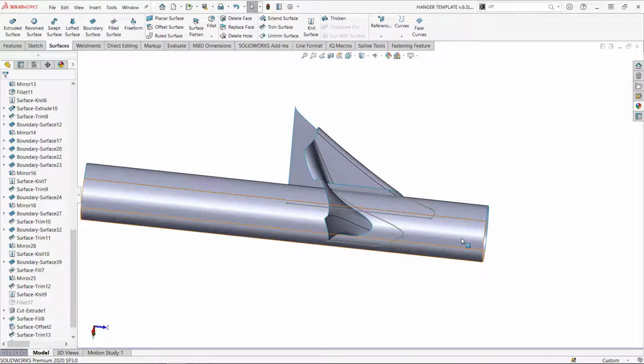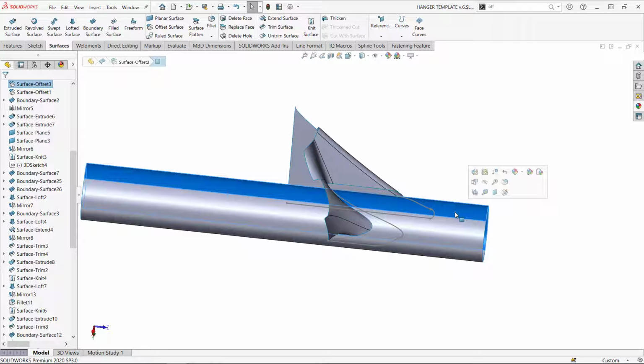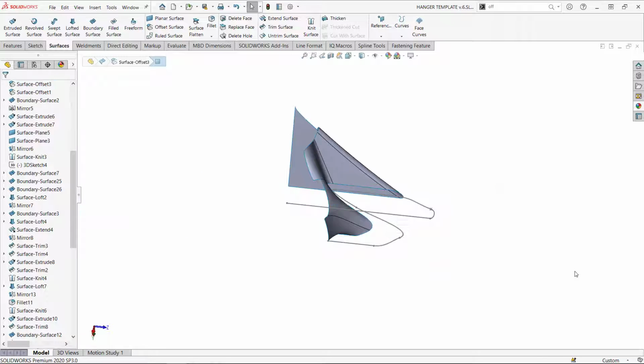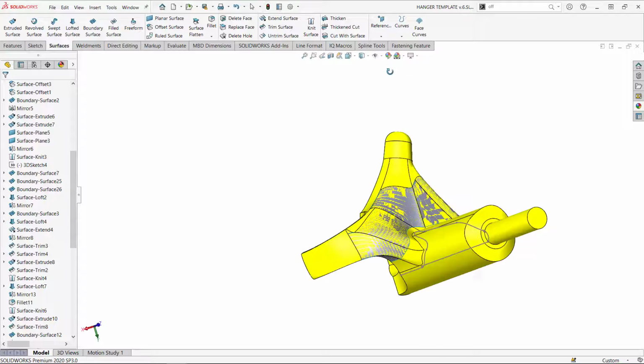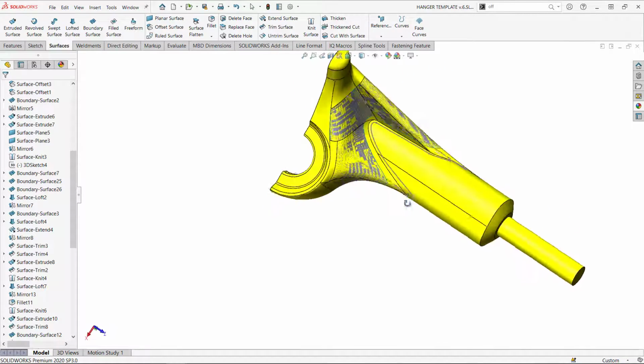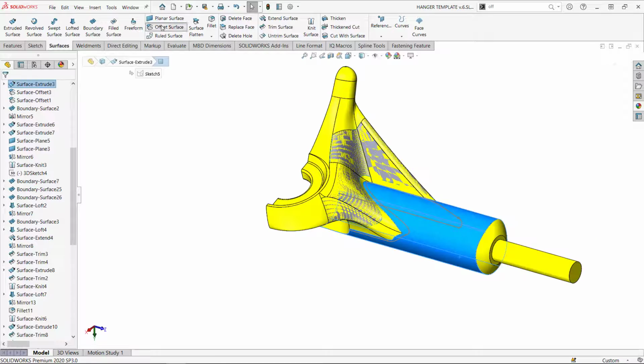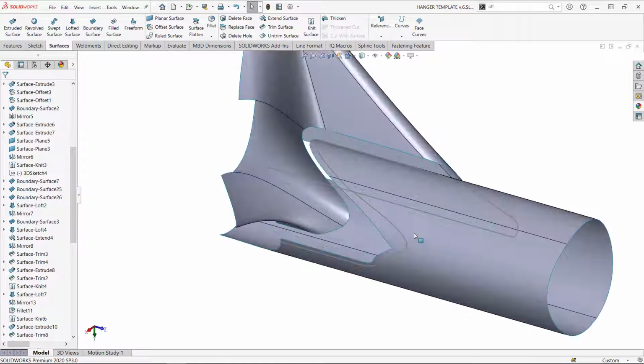Remember that we built this surface body just in order to be able to create this part of the sketch. So now it's time to delete the body or hide the body. For the time being, I'm not going to focus on deleting. I'm just going to hide it. Let's bring back the actual solid body, offset 0. So we use the divide and conquer principle, where we simply create simple subsets of faces for trimming purposes, blending, and almost like reverse engineering.